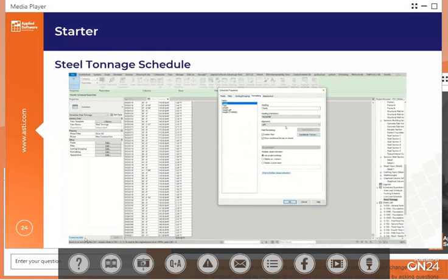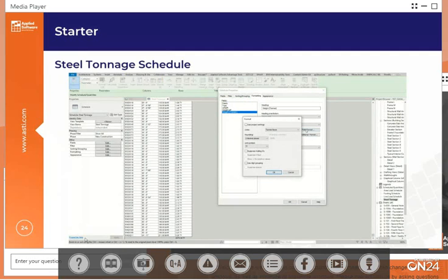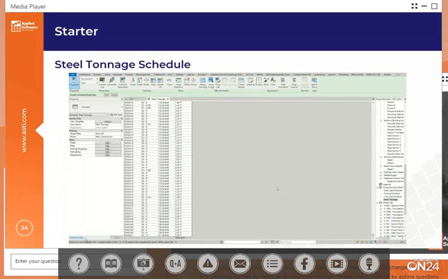If you look at the formatting, then we go to conditional formatting, and we just change that to 4. So even though it's pounds, Revit will automatically change it to tonnage for you. And we just ask Revit to give us a total, and at the bottom you'll see that it's a little bit more than 2,000 tons. So if the contract comes back saying 8,000 tons, then you know there's something off because that's quite different. They come back with 2,200. That could be the installation or the miscellaneous steel, but it gives you a good ballpark of what's going on in the building.